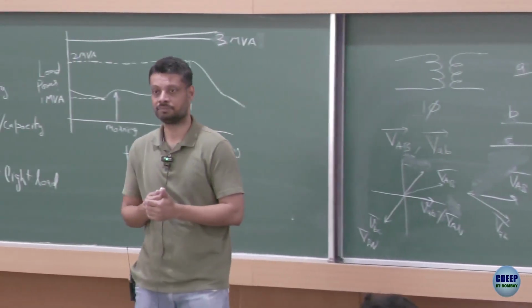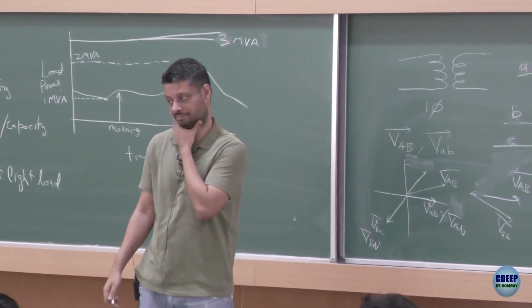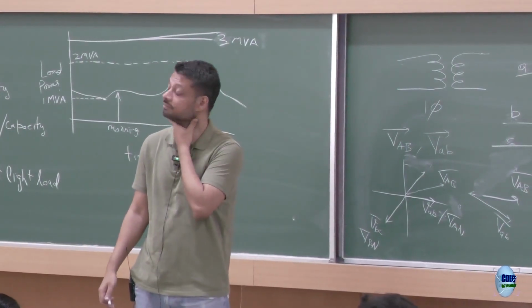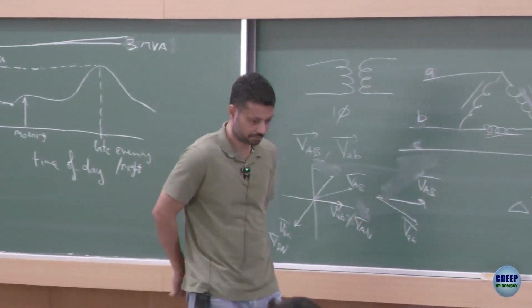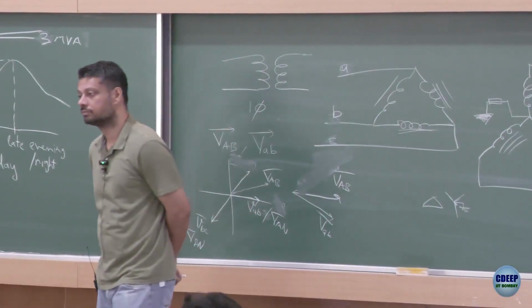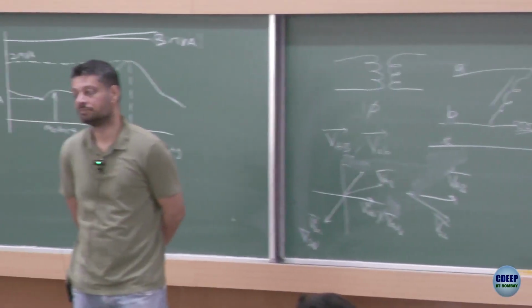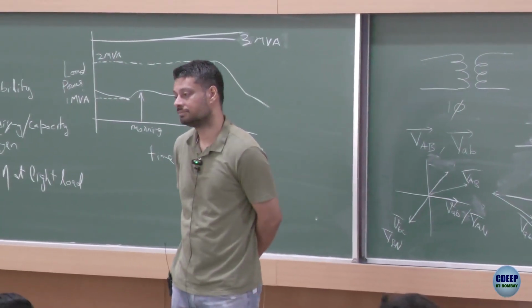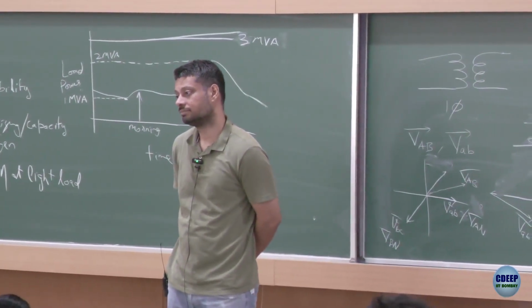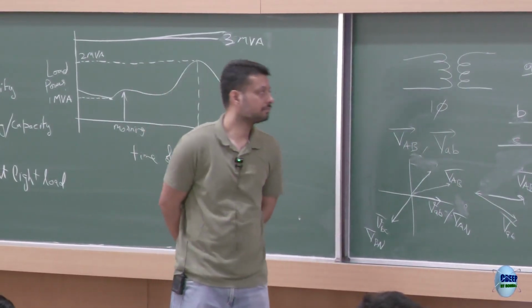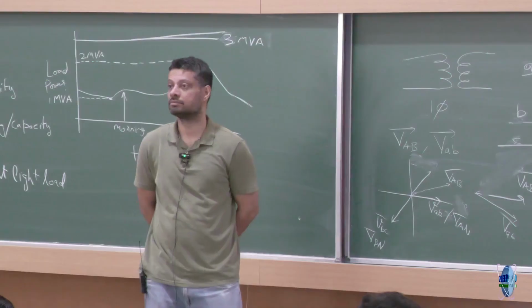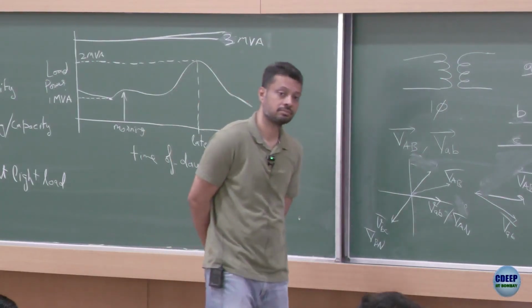Okay. Because we don't supply three phase, we supply phase to neutral, most loads are single phase, outside of like ACs or large loads. So we want a neutral for the load. Okay. We will use the star on the load side. And on the supply side, we don't need an extra wire that also carries large current, so we'd rather just have a delta connected thing.